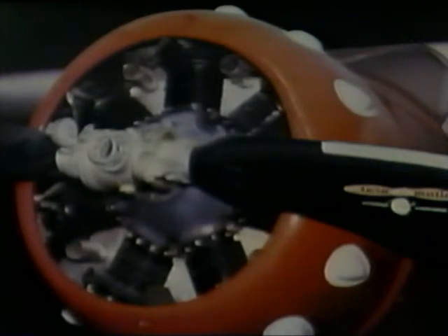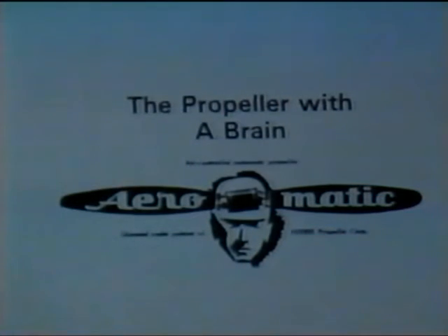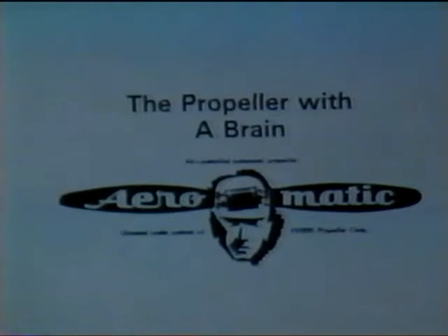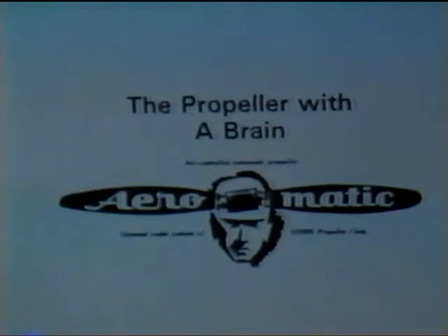Ground-adjustable propellers did not allow the flexibility of changing pitch in flight. One early design that allowed the pitch to vary during operation was the automatic pitch-changing propeller. Automatic propellers are designed so that the blade angle will change in response to operational forces as flight conditions change. At high power settings and low air speeds, as in climb, the propeller will respond by decreasing blade angle to provide good climb performance. There is no cockpit control as the propeller is an independent and automatic unit.